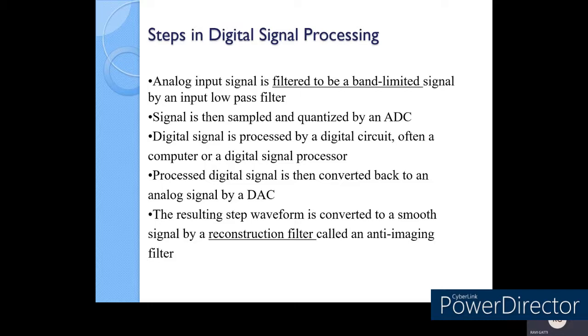One more important thing to study is that when we get an analog signal, we need to process it before the actual analog to digital conversion. For that we use a band limited signal, or a low pass filter on the incoming signal, and when we want to do data transmission we use a band pass filter. The frequency filters, or the band of frequencies we allow for our representation, play an important role in the frequency analysis of any given signal.